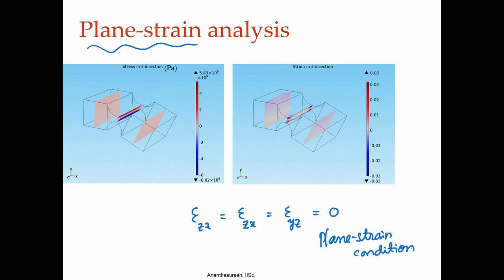Here if you were to do plane strain analysis, say you have a compliant mechanism that is very long, like usually plane strain elements are used for pipes, where along the axial direction of a pipe you do not have much change in the strain because it is so long, so this condition is valid.